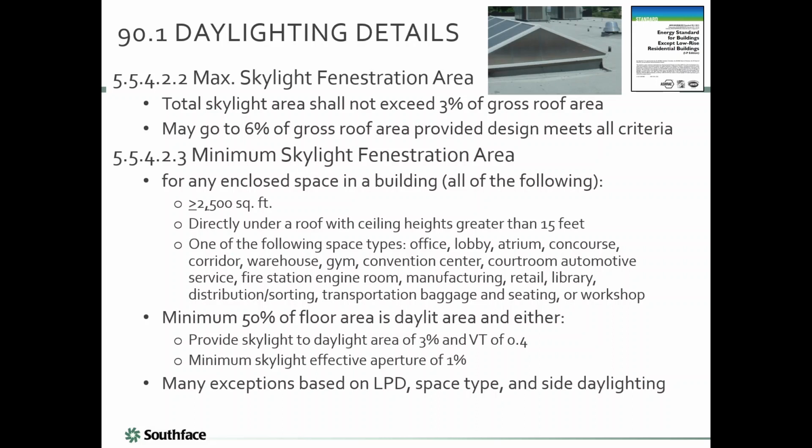That's perfectly fine. And Joe, what do you think the light fixtures in those natural daylit zones, how do you think they probably want those to be controlled? Probably need an integrated sensor with daylight sensor. Yeah, some kind of automatic lighting control. We'll see that when we get to the lighting section. But basically, anywhere you have natural daylight available, it really makes sense to have an automatic control, just like you said, that will take that light level down when natural daylight's available.